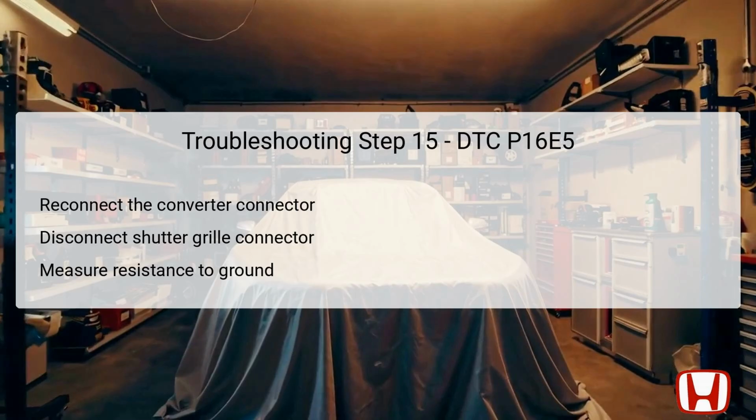Resistance of 1 megaohm or more indicates successful checks, while lower readings point toward potential malfunctions that may necessitate further repairs or component replacements.